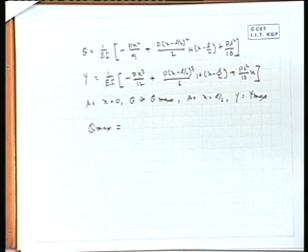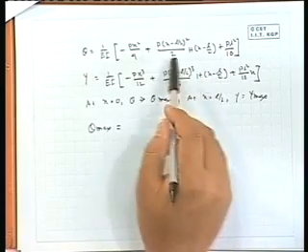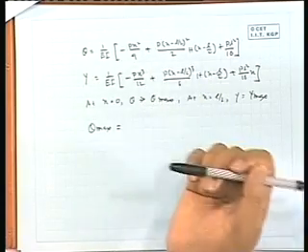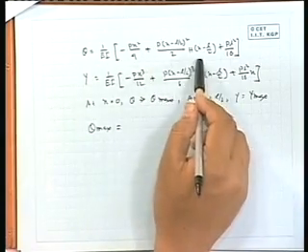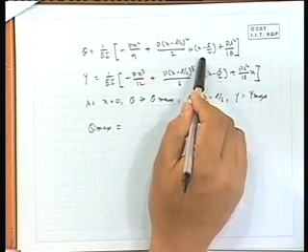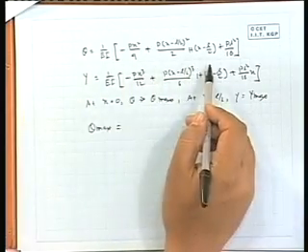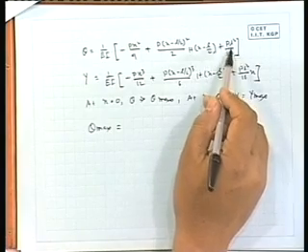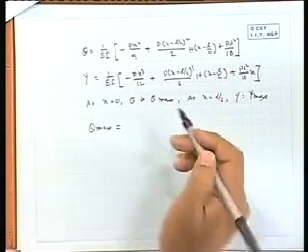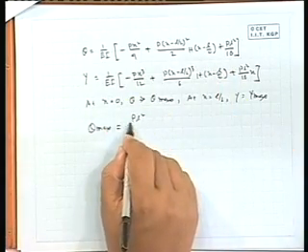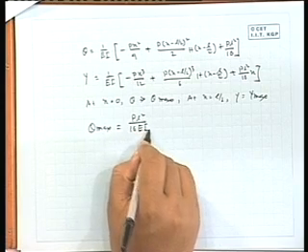In an automatic process there is a tendency to calculate something, but there is no point of calculating it because the step function will be 0 here. So, both the quantities will be 0 and ultimately PL square by 16 will remain, divided by EI, so that will be the value.